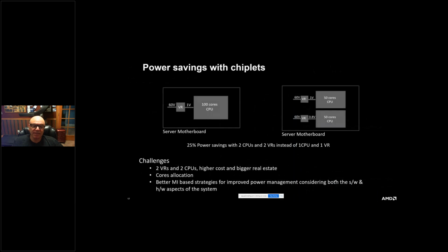Look at this situation. Let's say here you have multiple customers and you have one voltage rail. Suppose one customer wants to turbo. They want to run very high for some reason, for a few minutes, right? Because they want to turbo, they're going to take that voltage and raise it. But when you do that, you're going to raise that voltage on every customer, right? Even the folks who are idle are going to see substantial increase of power. I can't say you're idle, shut down, right? Like a laptop, for example, because one customer may be running turbo, but he's affecting the other customer who's not doing anything. So managing that at the data center in the multi-client environment is very difficult.